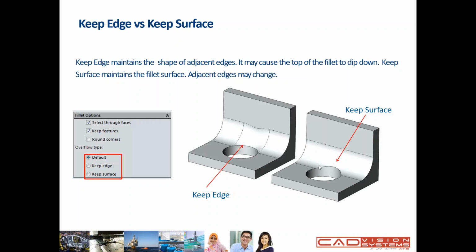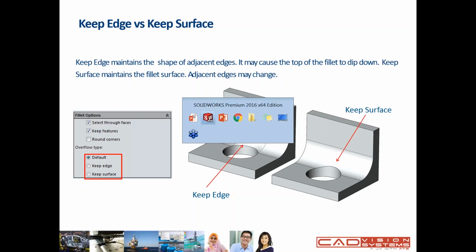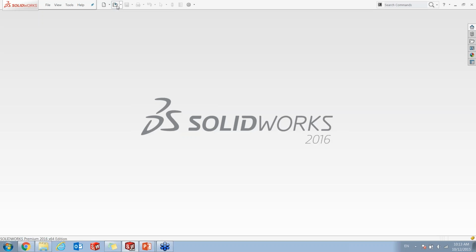Then you will change the geometry of the hole so that it allows the surface of the fillet to extend. You can play around with the option when you have such a situation that your fillet is very huge until it over covers a hole in this way. So in 3D it looks like this.